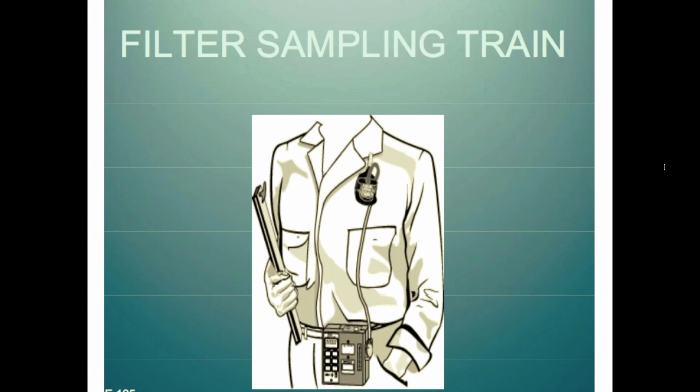You're saying that after the reading, you put in the calibrated filter in there to see if the flow had dropped. Yeah, in other words, you're going to have one of these that you're going to put aside and you're going to use it for your calibration. If I use this to measure the worker's environment, I'm not going to connect it to my calibration device and use it for my post-flow reading. I'm going to replace it with an ordinary cassette. It's not going to be exactly the same, but you don't want to expose this.